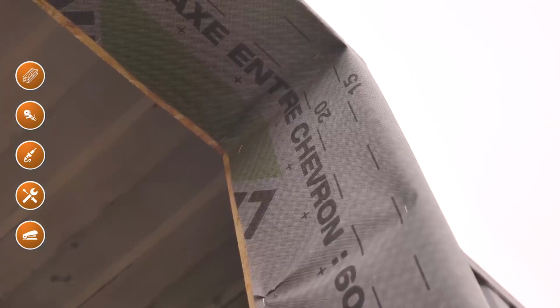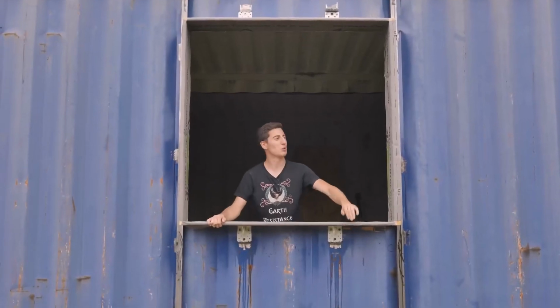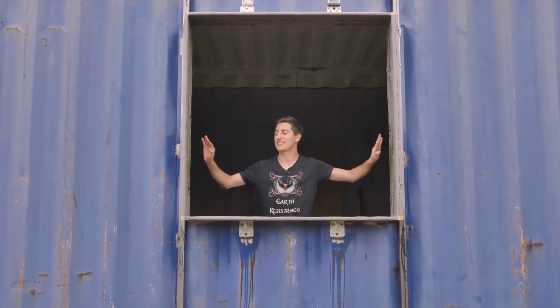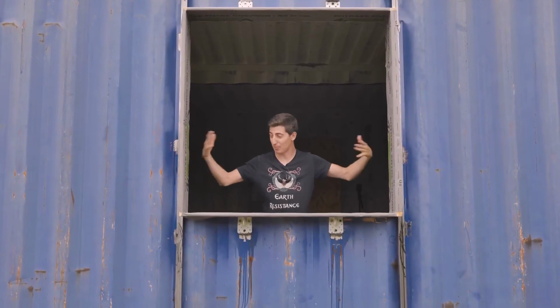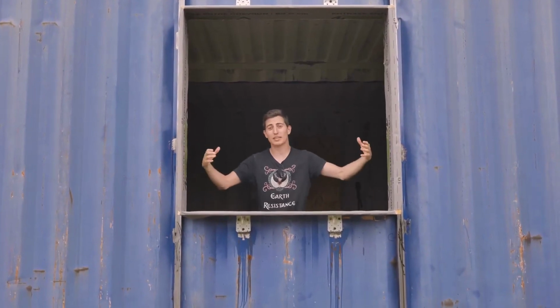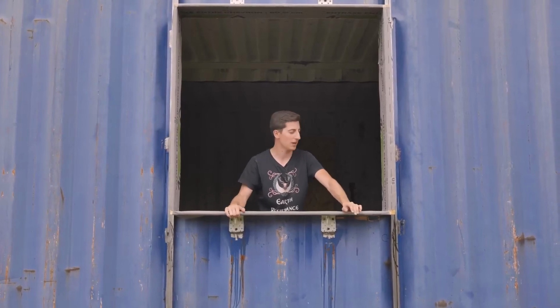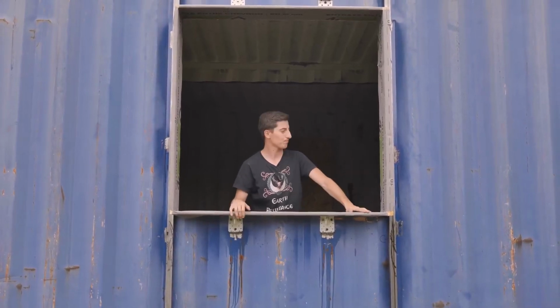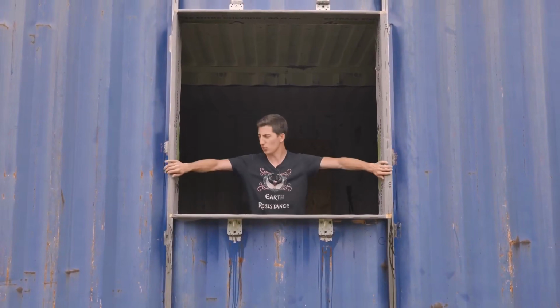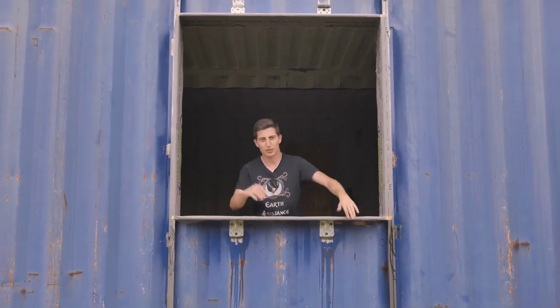There we go. Finally, after 4 or 5 hours of work, we've installed our oriented strand board tunnel, which will now be ready to receive our tunnel-mounted window. The procedure is nearly the same for installing a sliding glass door with only minor differences. I'm happy with what we've done. It's solid, square, level, and honestly really good.